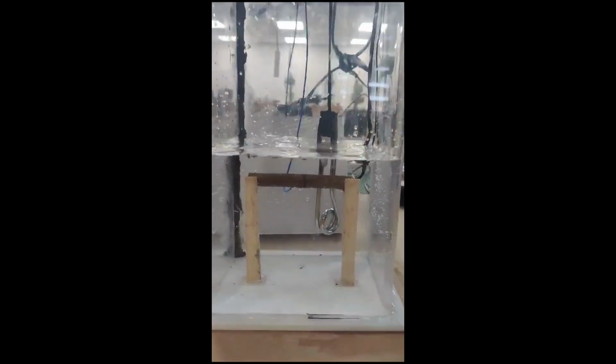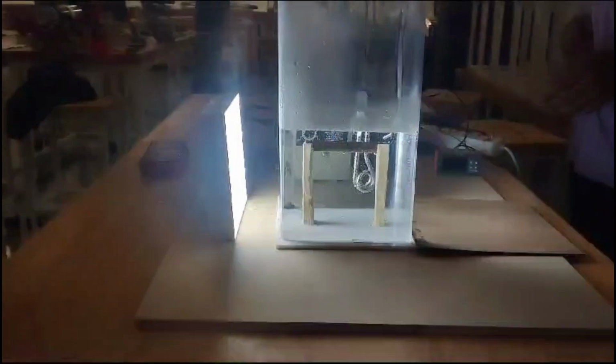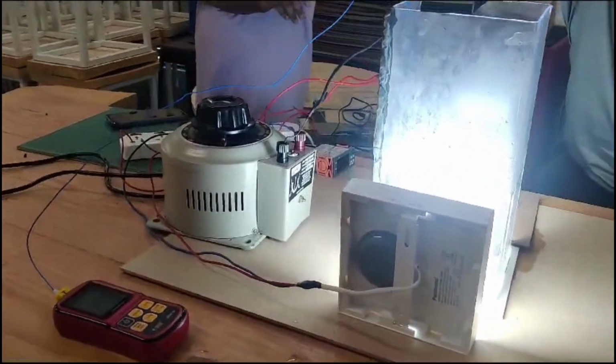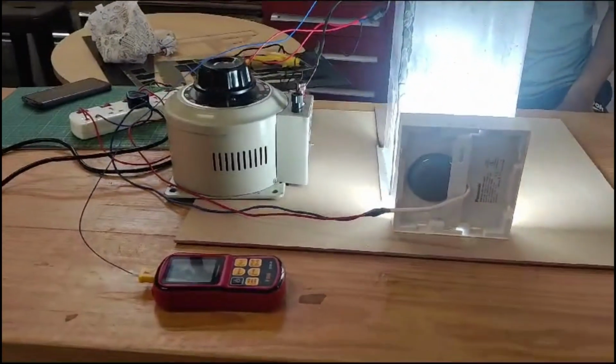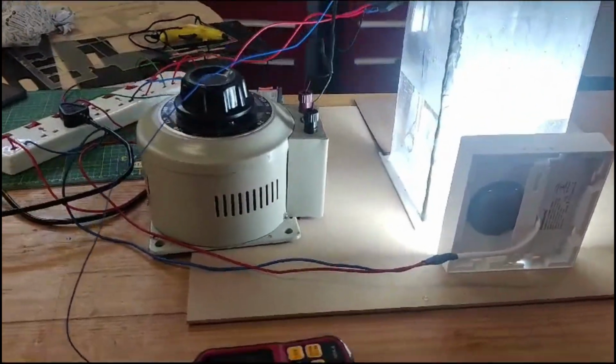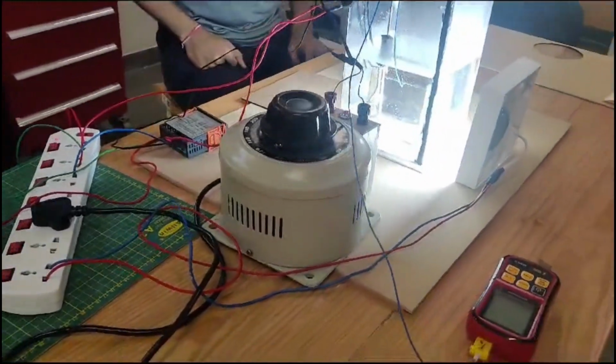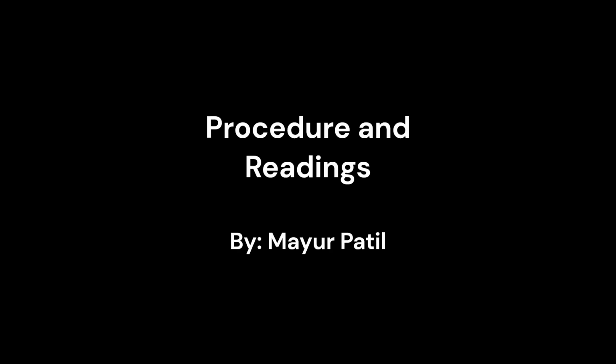This thermocouple measures and records the temperature of the rod surface during various boiling regimes. A microscope camera and LED light source are used to visualize and record the bubble dynamics during the pool boiling process. The camera allows detailed observation of bubble formation, growth, and departure from the test surface. This visual data is valuable for understanding the boiling process.